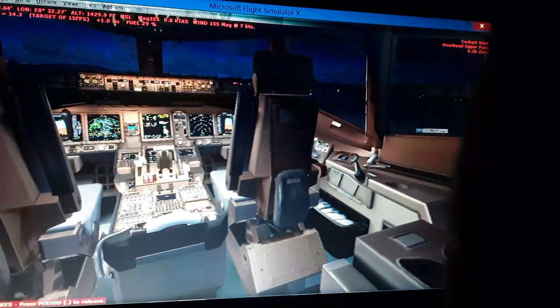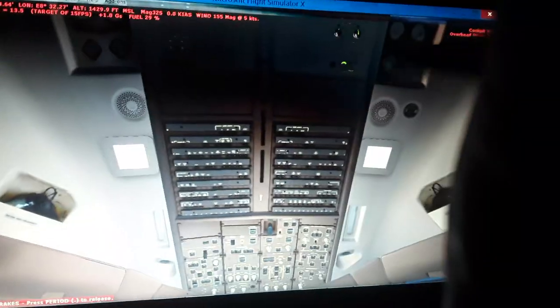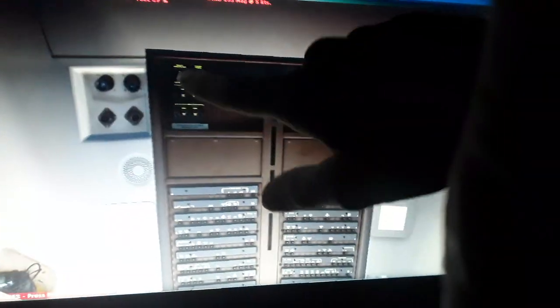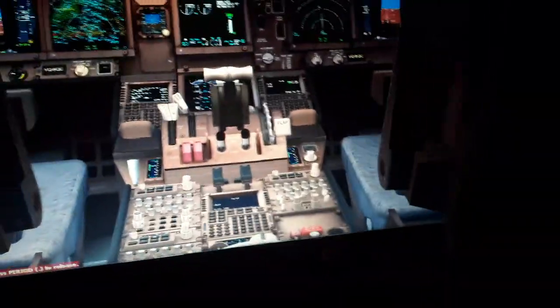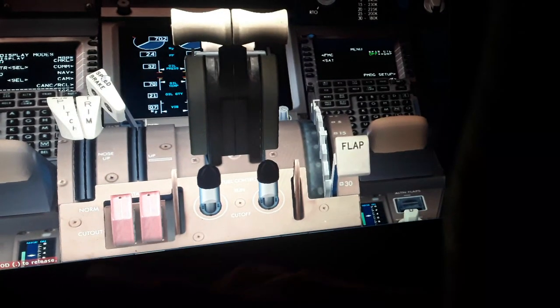So you can see here we have the panel, we have the cockpit, this nicer view. It shows more stuff. So you can see we have the hydraulic fluid for the flight controls, disconnect switch here for ground maintenance. We have the circuit breakers you can reset in flight if you have an electric failure. You have the same controls in this place again here.